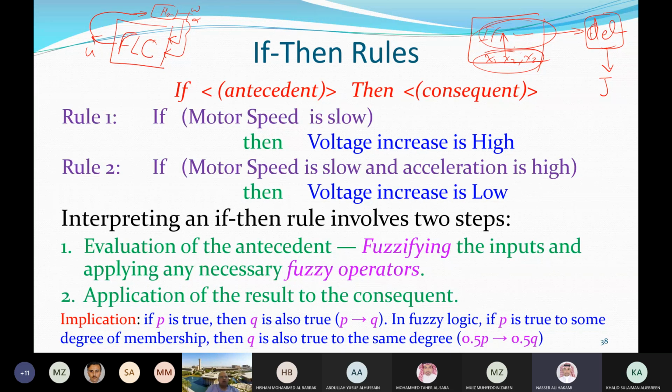As we mentioned, we define the omega and the alpha, the speed and the acceleration. We can define them as minimum, low, high, medium, very high, very low. And you can divide it as 7 values or 3 values or 5 values. It doesn't matter. And then you have some if-then rules here with the experience. Your experience is embedded here in if-then rules, and then you can take the action accordingly to the measurement. So this example would be very clear to explain how the fuzzy logic works.